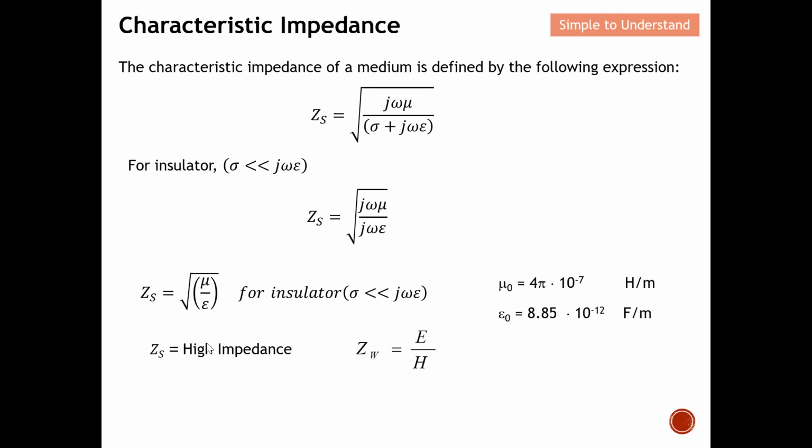Again, if this is high, and this is the electric field, which is also high, it may not be appropriate to attenuate away the electric field. But like I mentioned earlier, it makes sense. Any insulator doesn't have a reflection property, or maybe I should say it doesn't have a desired reflection property. Hence, we will not use an insulator as an EMC shield. We will use a good conducting material as an EMC shield. So this is what I mean.